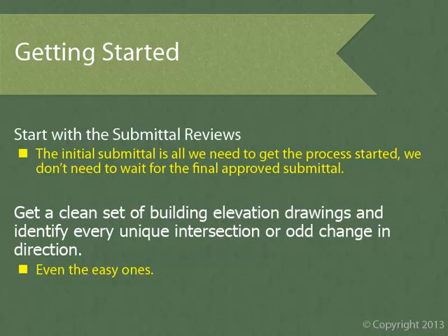For example, if you log 20 easy details and just one is randomly found to have a complication, then solving that one random problem makes it worth running quickly through all 19 of the other conditions. The fact is that conditions occurring only once often have more problems than the repetitive conditions. This is mainly because the design teams usually only detail the common conditions and leave the unique conditions up to the general contractor's exterior skin coordination effort.